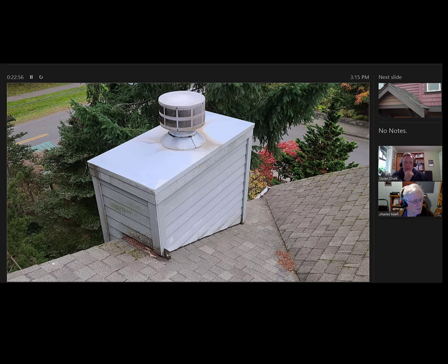And I brought up just a couple other slides. Redirect flashings are very rarely installed, and we could use them in these little spots on a chimney. If you're listening, this is a wood chimney chase that leads into the roof slightly. Water can run down the roof and hit the side of the chimney, and then it often just runs down the entire length of the chimney. It's fairly common to see a bunch of water damage at the base there, huh?